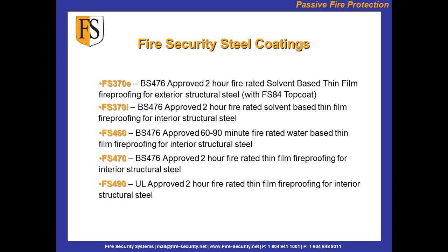Understood. So our FS460, which is British Standard approved as well, has a 60 to 90 minutes fire rating, water-based for interior. FS470 is our 2-hour. FS470 also has 60 and 90-minute ratings too, but depending on what element or what column or beam it is, we play between 460 and 470 to give the client the best option when it's under the 2-hour rating. So it can be an either or.